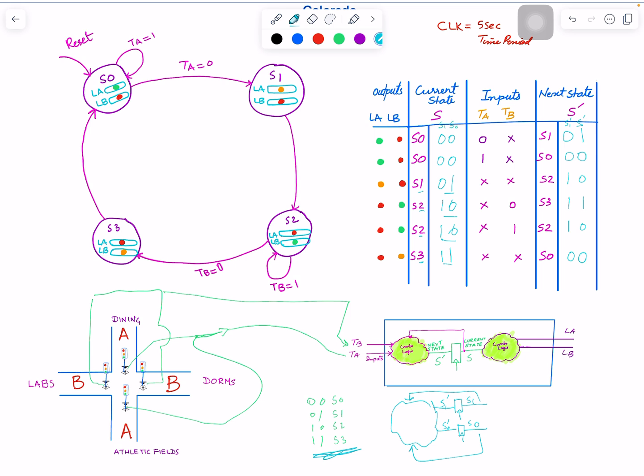So all we have to do is determine when S1 prime is 1; the inputs are these two and these two. Similarly, we have to determine a digital circuit for S0 prime, which is this one. So now this problem goes back to where we started: combinational circuits, truth tables, determining the Boolean equations, and creating a very simple circuit for each one of those. We will get to that. So we will determine this. I think from here the problem will be simple.